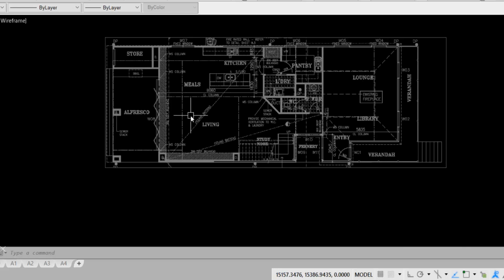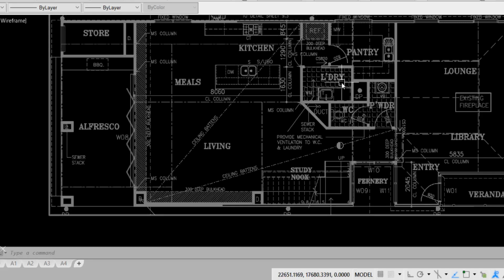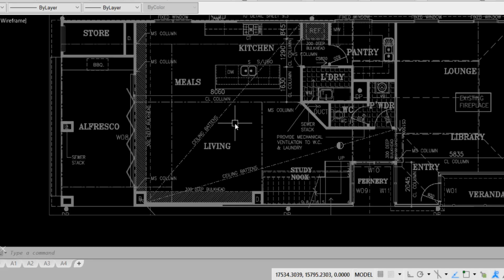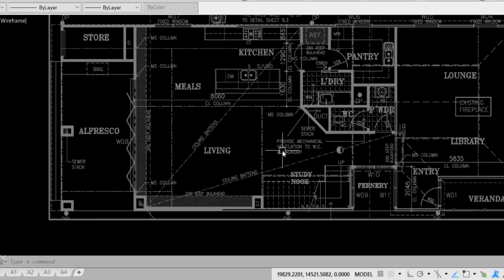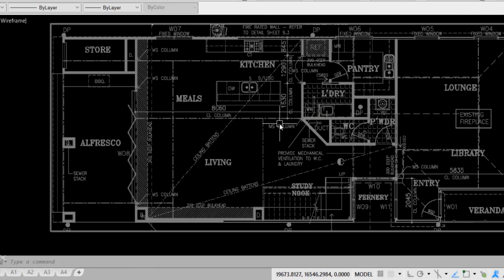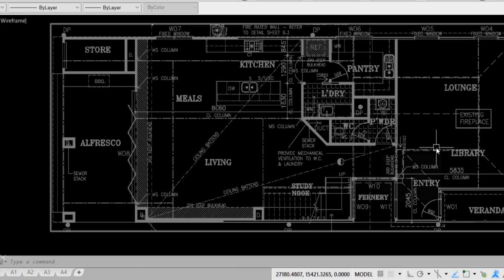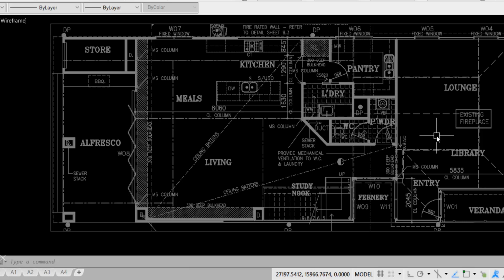This plan, you can see, has quite strong drawing lines. And so I'm going to make a modification to the layer that the PDF is in, and make it more transparent so that this plan fades a little bit better into the background, and it will be easier to see on our 2D plan the difference between our 2D scaffold and the floor plan.